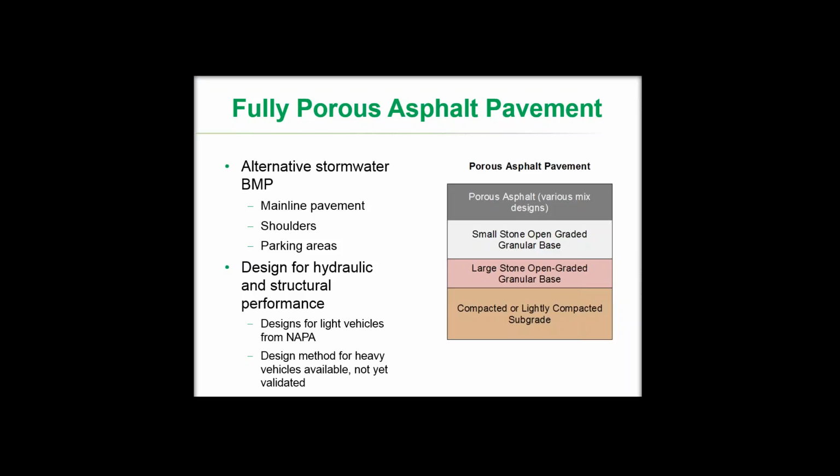These need to be designed for hydraulic and structural performance. There's a design manual from NAPA that's available, and there is a design method that's been developed for heavy vehicles, developed for Caltrans, not yet validated, but there's work going on to be able to carry heavier vehicles on this type of pavement.